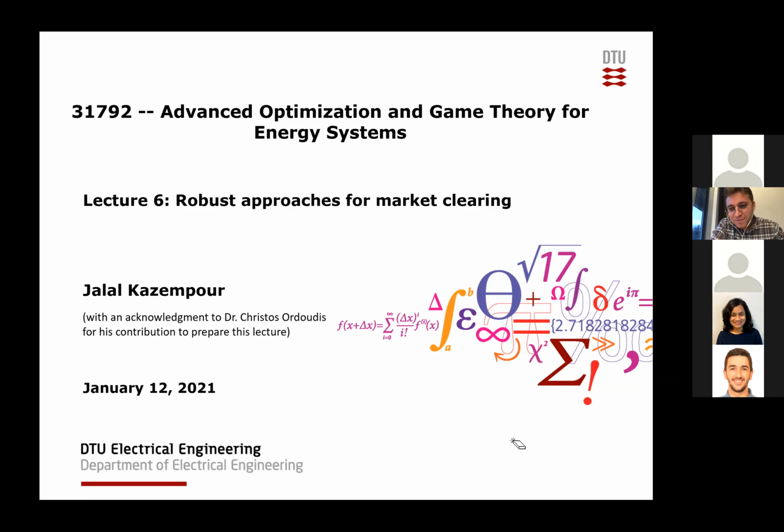So if we solve our case study example based on stochastic market clearing, stochastic programming, the results are a bit different than in the previous lecture because the scenarios are a bit different. But we end up with this day-ahead dispatch: 60 by the cheap generator, 30 by the expensive generator, 30 by wind. All demand is fully supplied, and the corresponding operational cost in the day-ahead stage is 1,200, because the production cost of G2 is $20 per megawatt hour. So it's 30 times 20, it's 600.